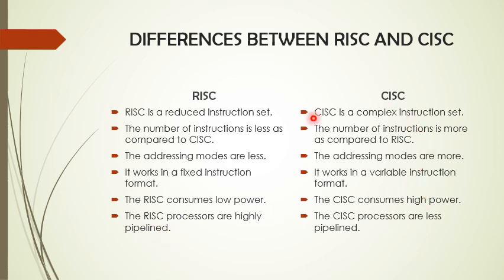CISC is a complex instruction set. The number of instructions is more as compared to RISC. The addressing modes are more. It works in a variable instruction format. CISC consumes high power, and CISC processors are less pipelined.